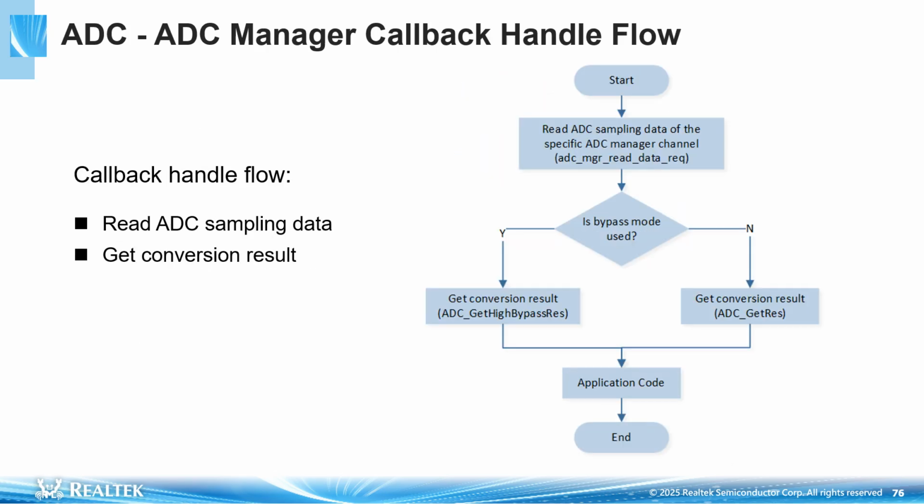When ADC sampling is completed, the callback function registered with ADC Manager will be executed. In the callback function, first read the ADC sampling data, and then get the conversion result.